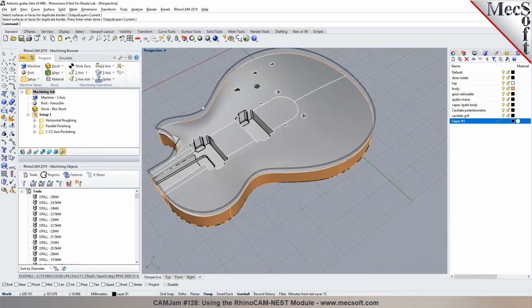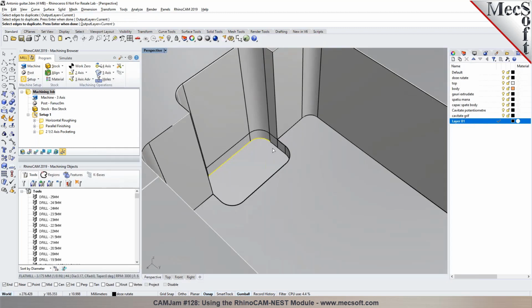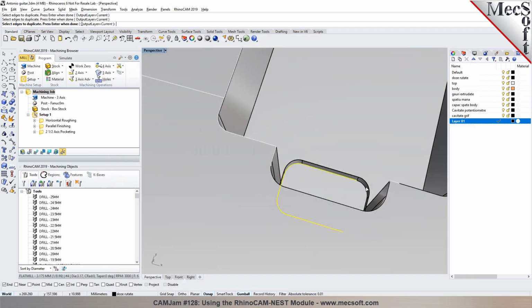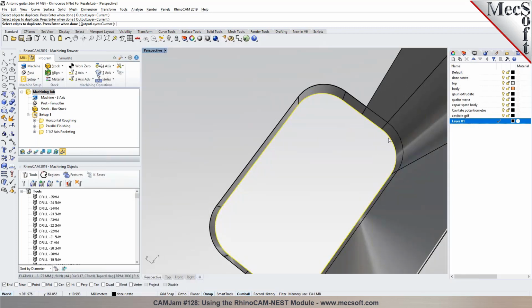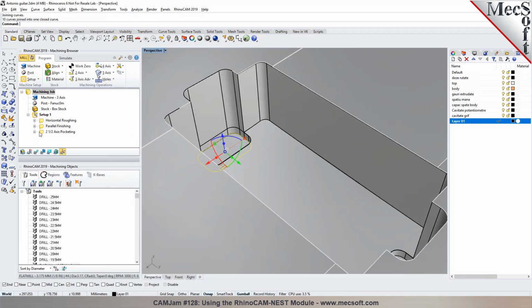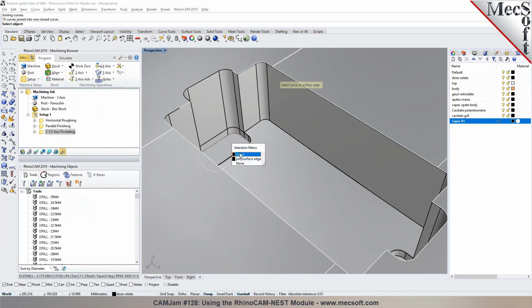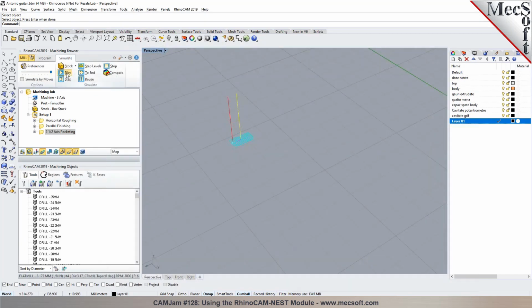So you can use the duplicate edge command in Rhino to create it. You can just go ahead and select these edges from the model. And then you can join them to be a closed curve because there are some gaps right there. It says 10 curves joined to one closed curve. Now I can go back in here and just pick this closed curve for containing the toolpath, and you have your pocket finishing toolpath. So that's how you go about programming it.